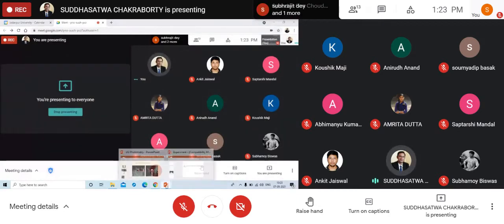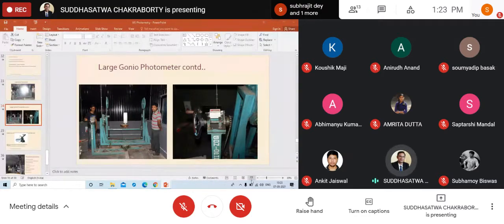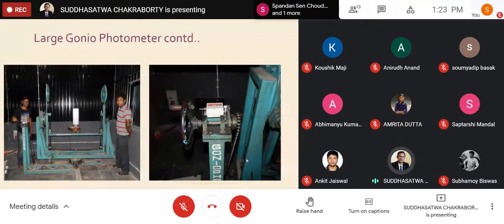We should ensure that movement, that is C gamma, B beta. No matter, this is a B beta type of coordinate system. I have already told you, but again I want to tell you one thing: it doesn't mean that we will always be going by B beta. Say I have a flat light luminaire, then I can comfortably measure using the type B goniometer. But unfortunately, if I don't have a goniometer which can measure the C gamma system, and somebody has given me, say, an indoor luminaire or a street light luminaire, what should I do? Will I not be able to measure? Yes, I can do this, because here only a 90-degree shift is required in the vertical plane.